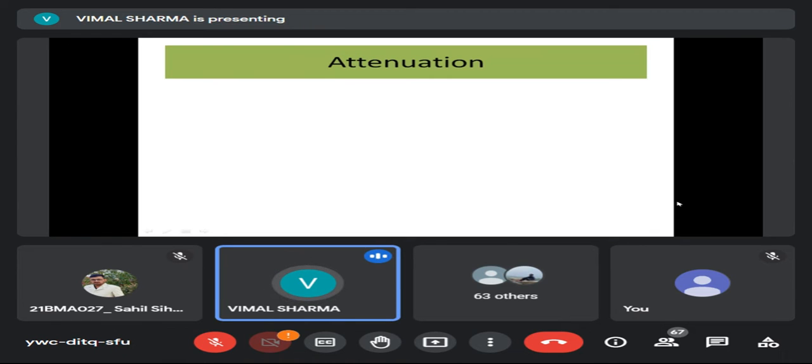Launching of light is also important. It is not only propagation of light. Propagation depends on the combination of core cladding refractive indices. But how we launch light from outside, that we discussed, and we said that the acceptance angle plays a role here. It is not that every ray we try to launch propagates through the optical fiber. It is only those rays which undergo total internal reflection at the core cladding interface.